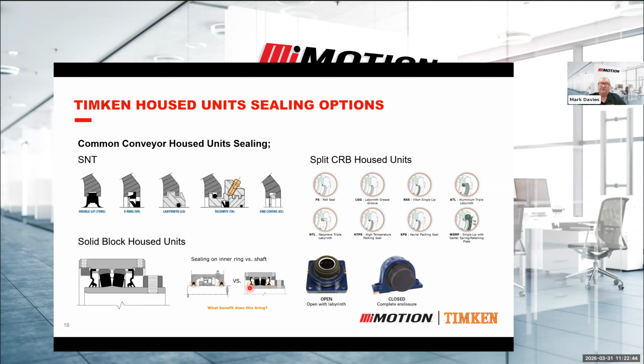So again, not shaft wiping, it runs on a hardened, ground steel surface, which gives a very effective seal. On top of that, you can add external covers as well, to give further protection. In my experience, this is an extremely good off-the-shelf solution for improving sealing capability.